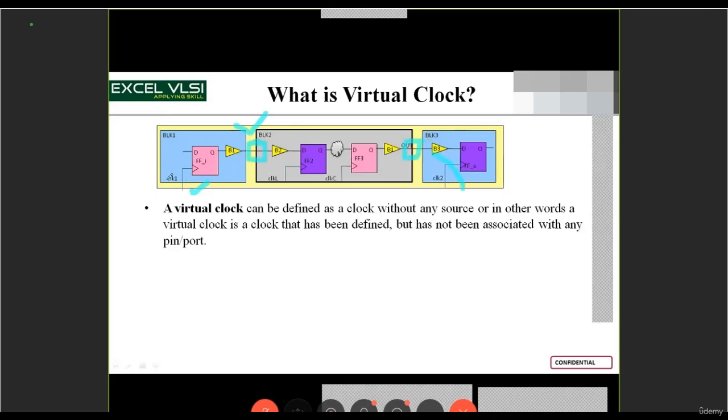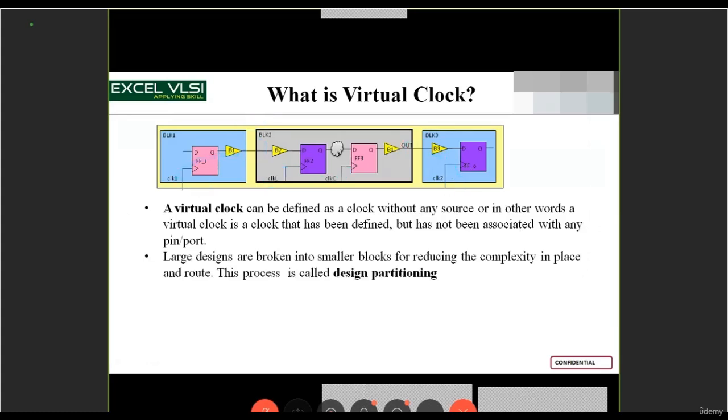These are just the reference clocks with which data is getting launched till my ports. Those clocks should be synchronous with respect to clock L and clock C. So clock 1 is the virtual clock at the input port and clock 2 is the virtual clock at the output port, where I'm assuming the frequency.